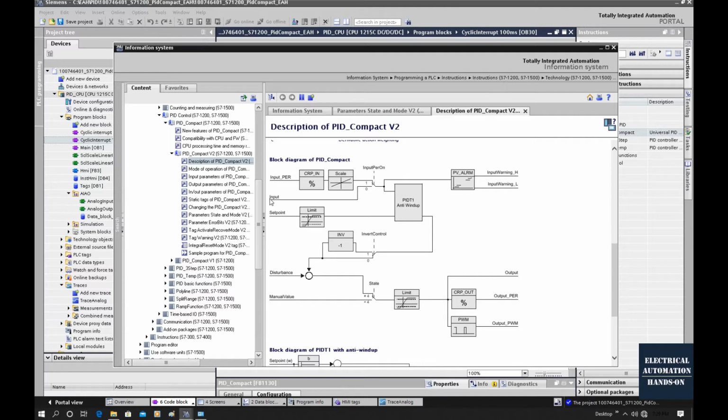And this process value will be used for alarm, compare, and multiple purposes. So we will scale the analog input offsets of the PID function block and connect the converted float value to this input of the PID. And that input PER on is a switch between these two channels. By default, that will switch to this channel.